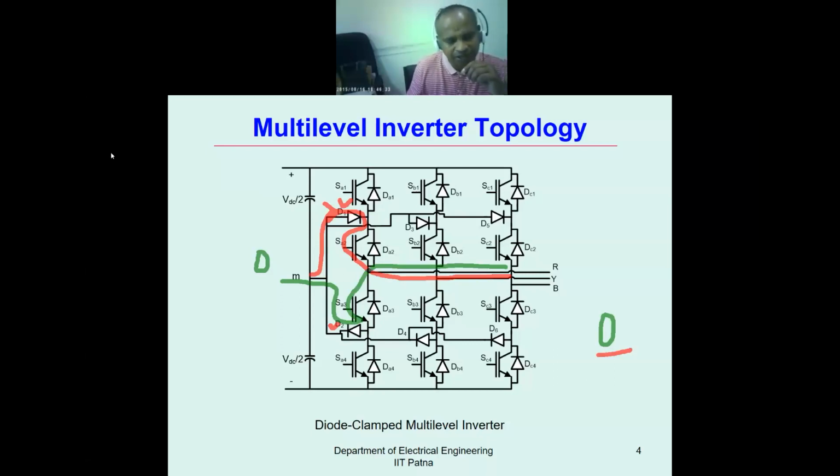Okay, if you have any doubt in the middle, just clarify, because we are going to design these multi-level converters. We will not do the design with two-level converters. We will use multi-level converters for all our design aspects. That is because it is a transmission line, and we handle 400 kV and 100 to 400 megawatt. So the multi-level converters are preferred.